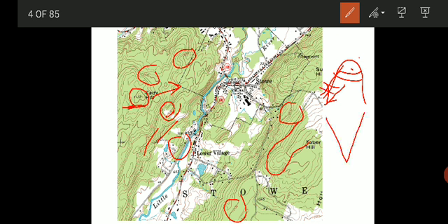The reverse is the case for a valley. The lowest contour will be towards the ground. Suppose this is 200, then 300, like that the contour values go on increasing away from the center. So if the value at the center is lowest, that shows the area is a valley.